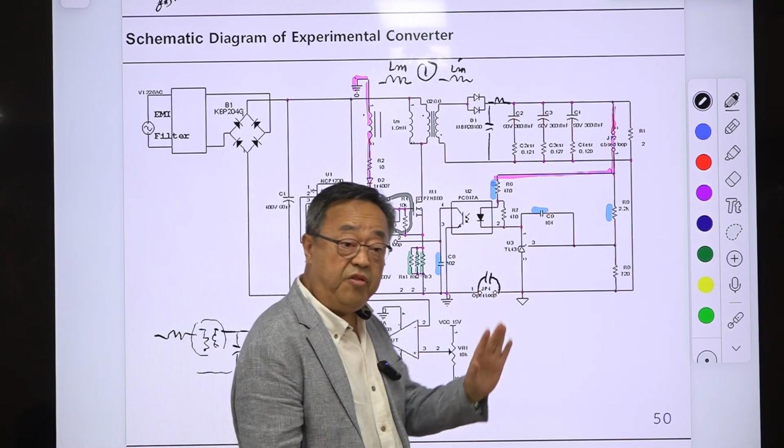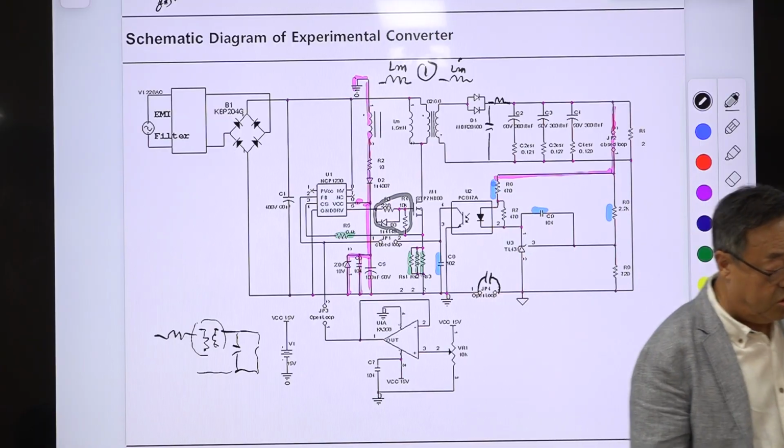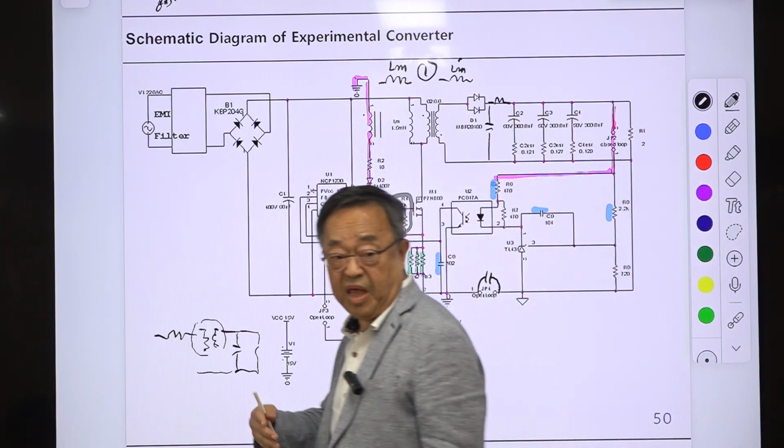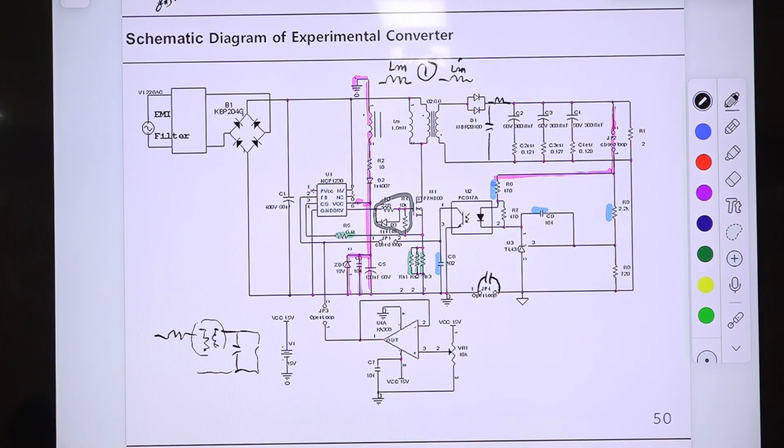When you are distinguishing between small and large capacitance, a good value is 0.1 microfarad, or 0.01 microfarad, as the borderline. Beyond that you consider it a large capacitor, and maybe some nanofarad or picofarad can be considered a small capacitor. Some student asked about this. He is not here, I think.